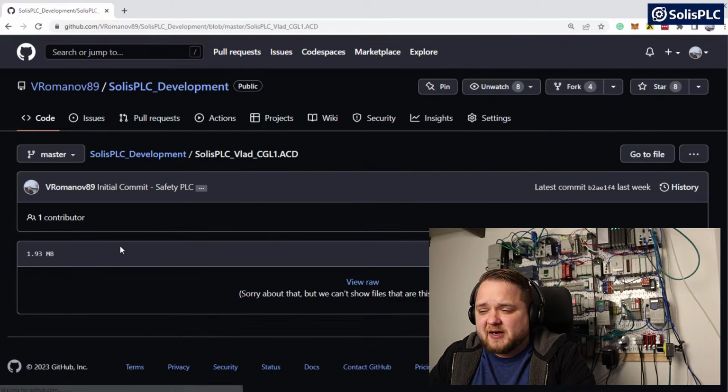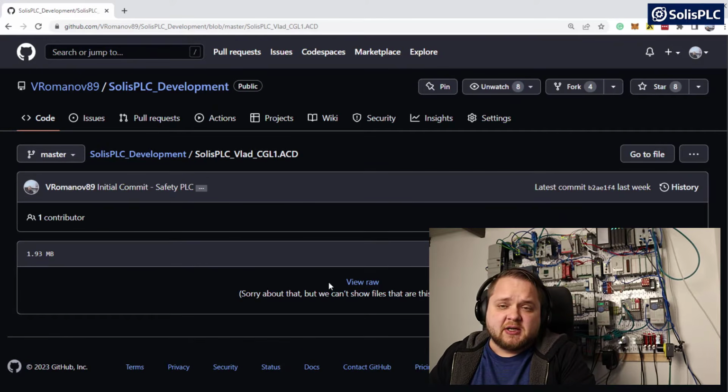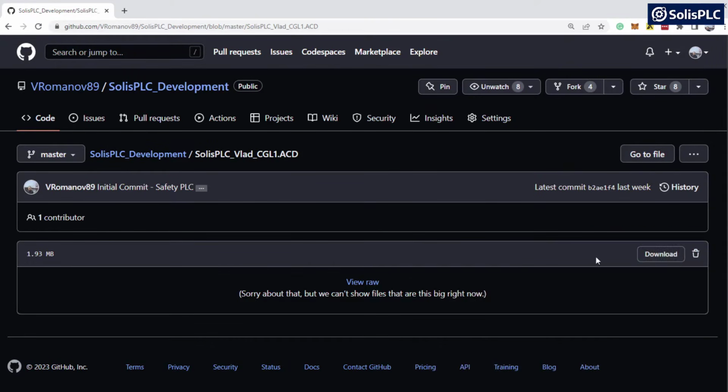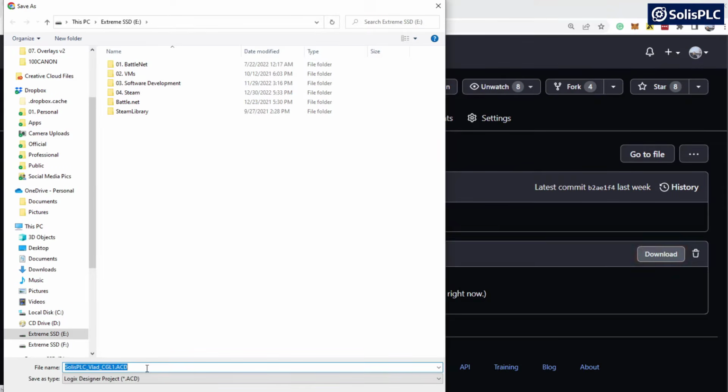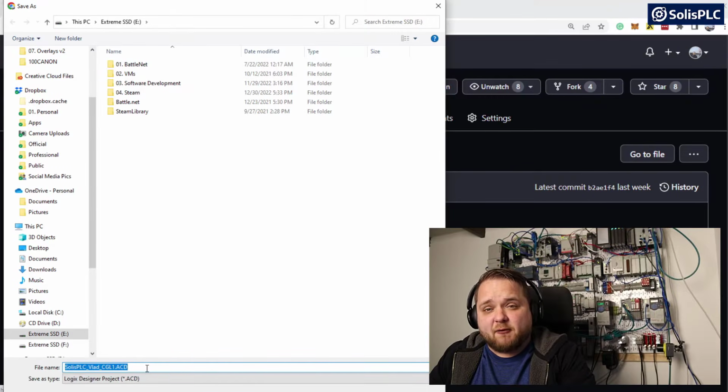So you can click this file and you will be brought to a blank page. That's because GitHub doesn't necessarily showcase PLC files. That is a whole separate discussion. That being said, at this time, you can download the latest file by clicking on this button right here, and you will notice that it will save just that one file in .acd format, which you can then open in RSLogix or Studio 5000. If you want to work in the exact same revision, you'll need a controller at that firmware, but you can always switch the file to a latest or earliest revision if you choose to do so.